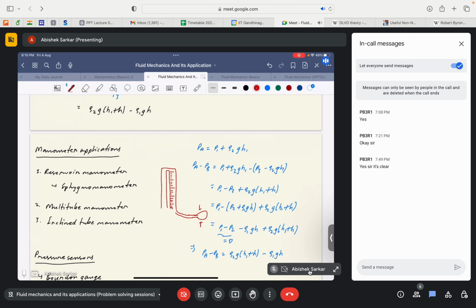At different points along the surface of the airfoil, a manometer or piezometer was inserted, which essentially gave us the value of the pressure at those different points, and showed us how the pressure varied along the surface of the airfoil, right? There were different pressure points being made, which were connected through manometers, right? And these manometers gave rise to different liquid heights,